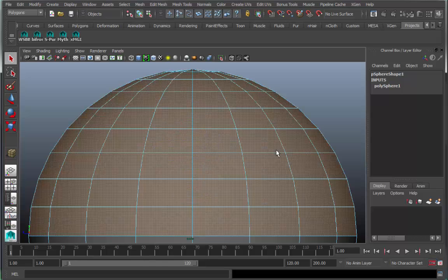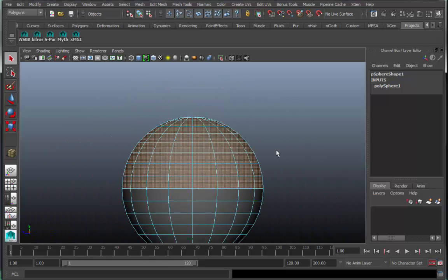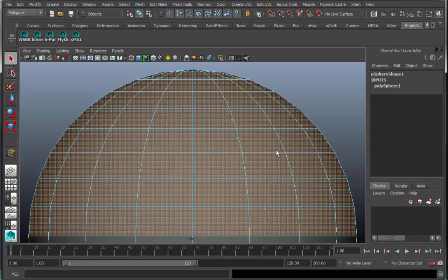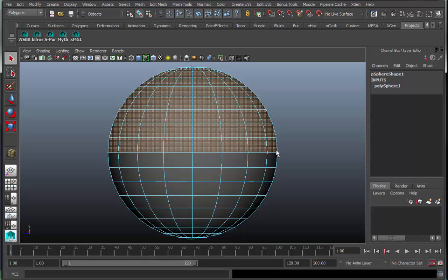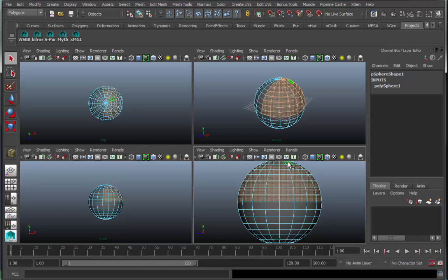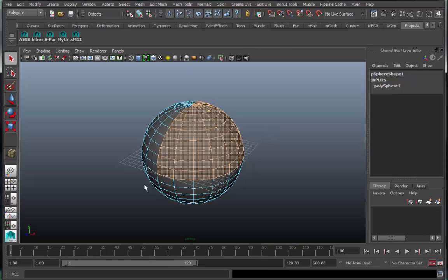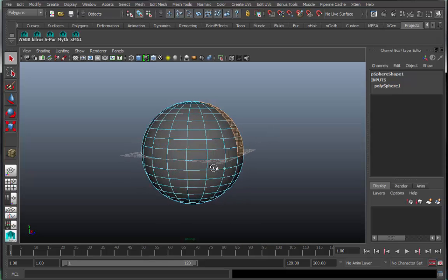And with the upper half of those polygons selected, here I am pressing F so I can frame what I have selected. The hotkey for frame all is A. The hotkey for frame what you have selected is F. And you can see it works in component mode as well as object mode. So with the upper half selected, I press the space bar to come up here and verify that, and oh look, it did not select the other half here.